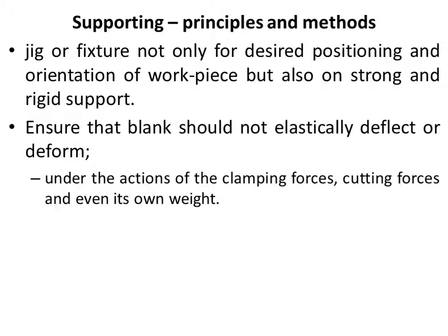So this is how the 3-2-1 principle is employed to ensure that the position of the blank will not get disturbed by the applied cutting force. We get a very consistent location of the component and the accuracy is ensured on the component.